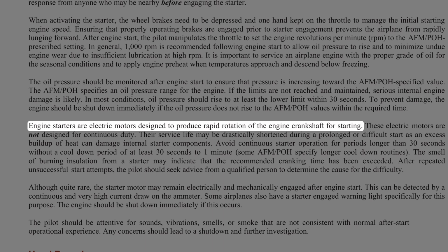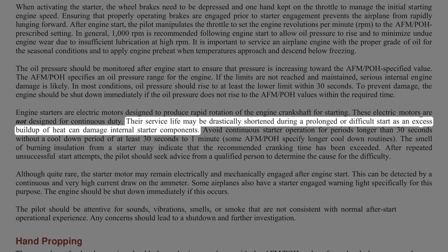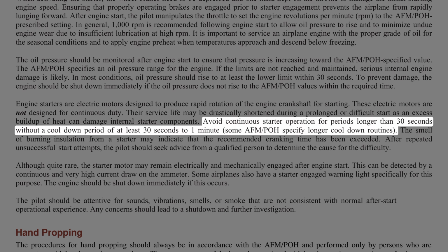Engine starters are electric motors designed to produce rapid rotation of the engine crankshaft for starting. These electric motors are not designed for continuous duty. Their service life may be drastically shortened during a prolonged or difficult start, as an excess buildup of heat can damage internal starter components. Avoid continuous starter operation for periods longer than 30 seconds without a cool-down period of at least 30 seconds to 1 minute.